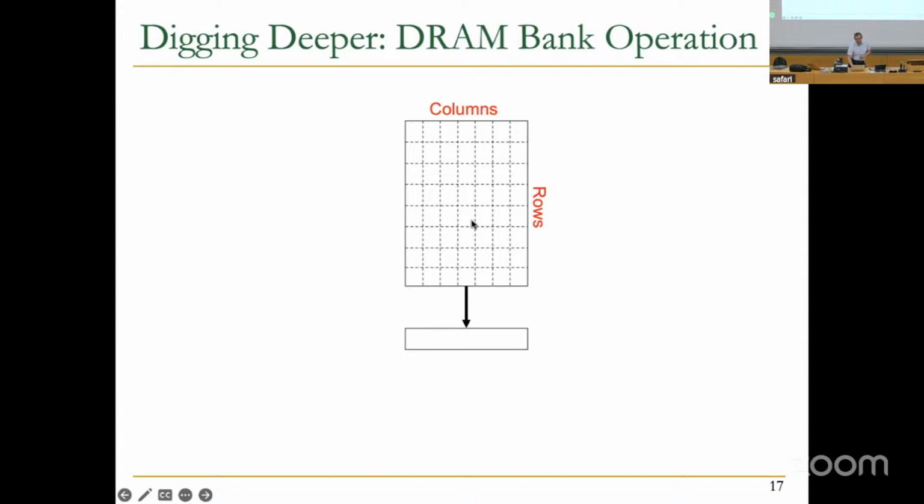After you supply the row address, the data needs to be sensed using sense amplifiers. The sense amplifiers are also called a row buffer. We're going to see this a little bit more in detail, how this is built. It's actually built using SRAM-like cells, cross-coupled inverters. Initially, you have nothing to sense. You didn't access this array.